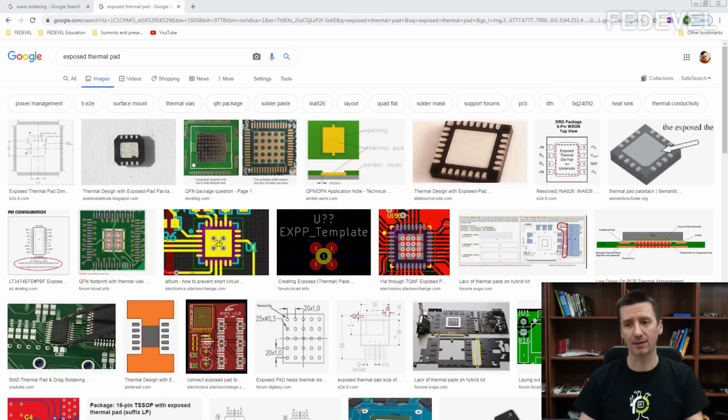There is one more thing I wanted to know, and it's about this kind of exposed pad. In some chips, they use an exposed pad with a piece of the corner cut off, and in some data sheets they recommend the land pattern or the footprint with the exposed pad and with this corner cut off. It's quite difficult to create this kind of special pad in the footprint. So I wanted to know if it's really necessary to consider this cut off corner in the footprints.